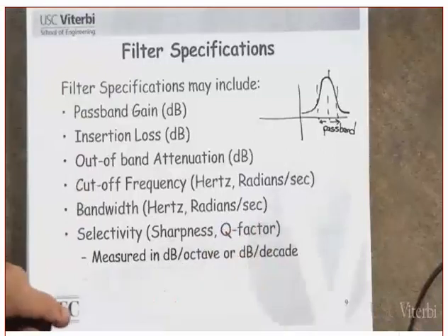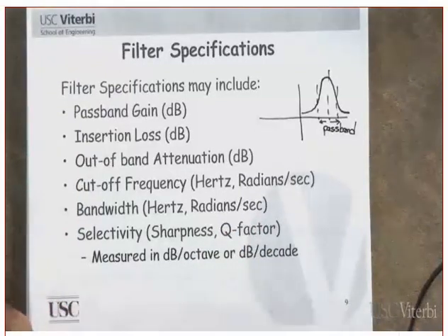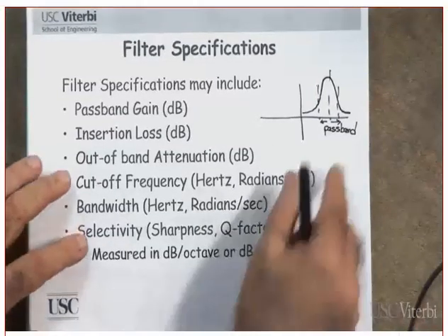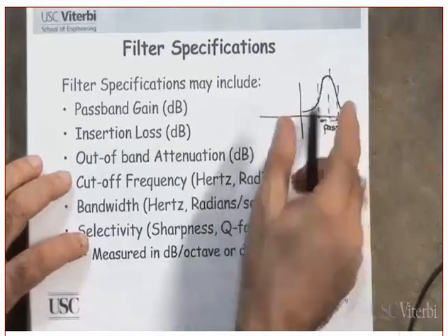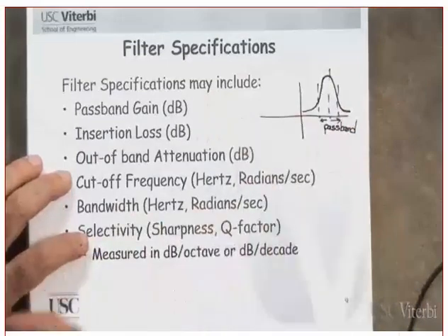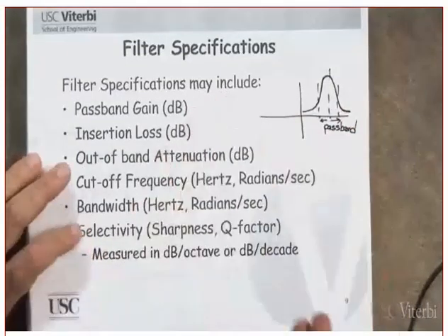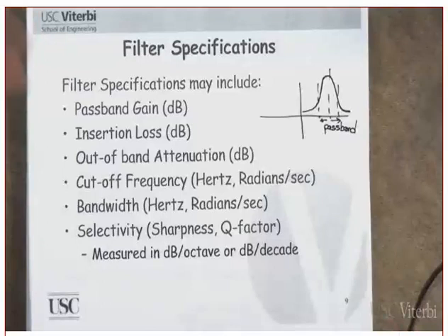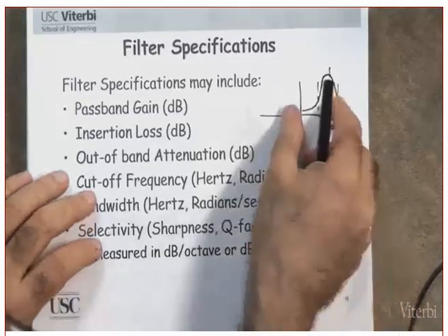Where is the gain? Now you might tell me, why is there a gain? It's a filter. The filter does not need to be a passive filter. It could be an active filter, which means it's actually an amplifier, but it's also providing selectivity. We call it a tunable amplifier. Clear? It provides gain, but it also provides channel selectivity. It selects a certain channel.